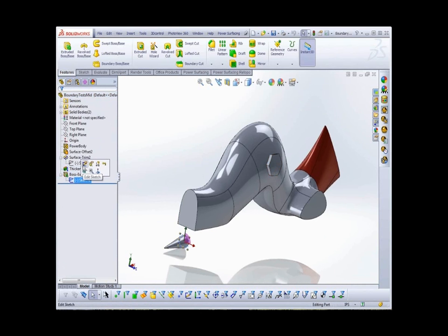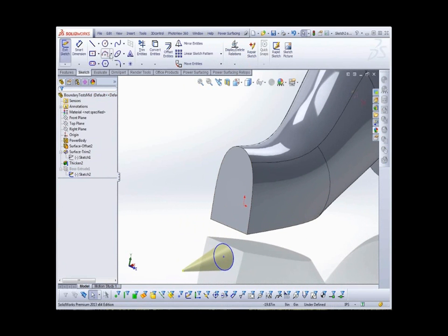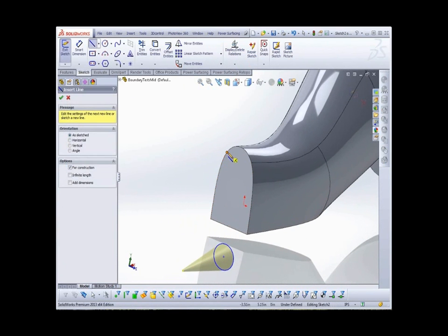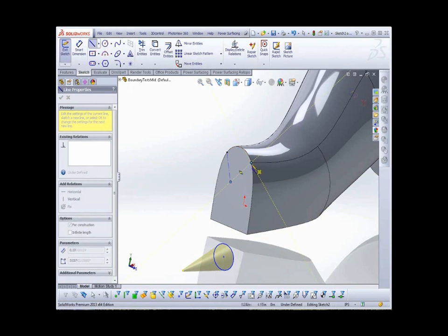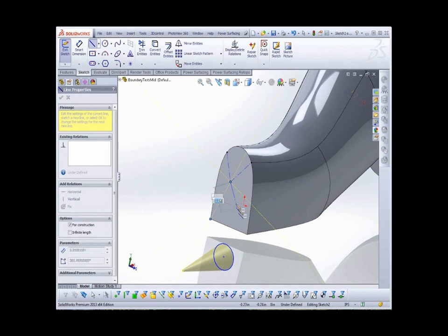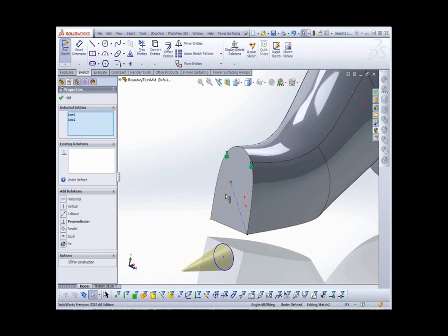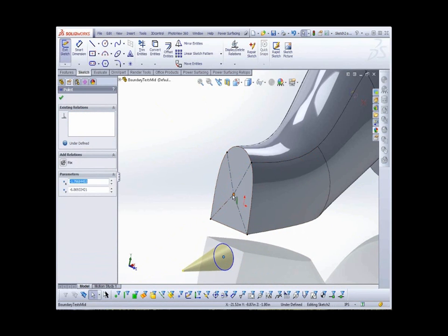And edit the sketch by adding a few construction lines that will have relationships with the points. I'll make them equal length and then merge the circle's center with their meeting point.